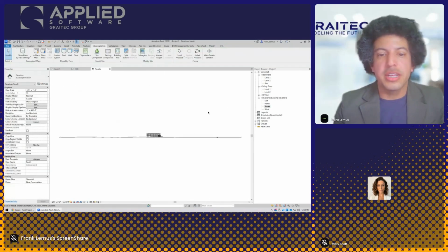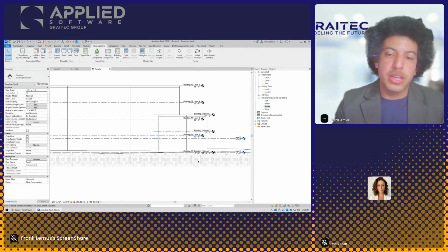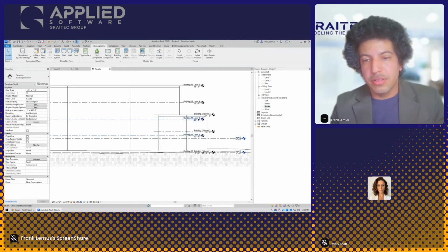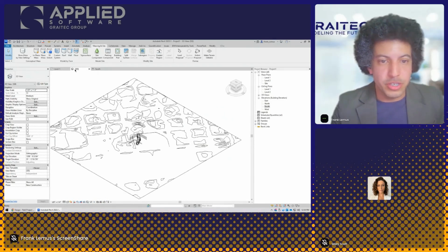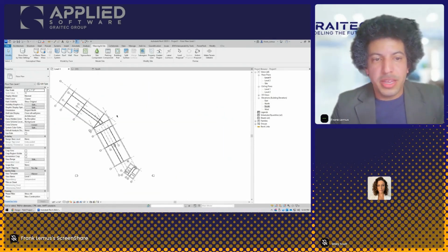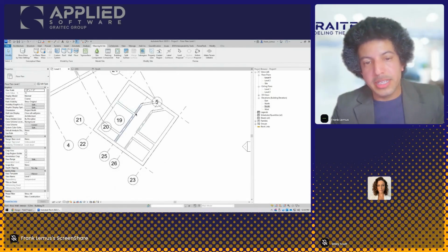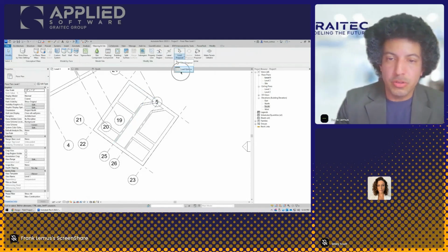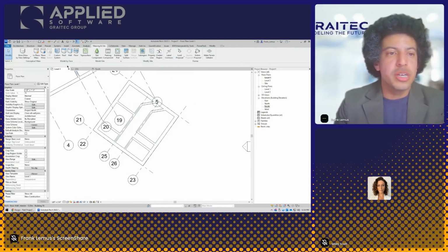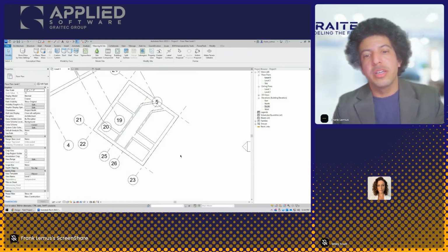And it is actually creating levels for you as well, but it's not creating views. So be careful about that. Obviously, the names are very off, so you'll need to determine a way to handle that. The takeaway here, though, is see how there's our design right there? It's creating actual walls for you if you set that in the settings right here, load proposal, load options. Otherwise, you would treat it as a conceptual map where you can then select things to create them into walls, floors, and roofs.